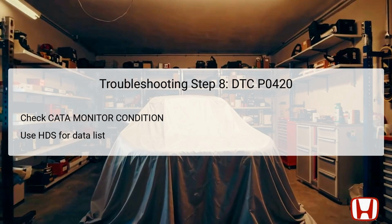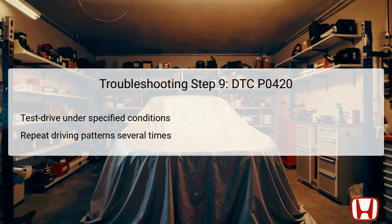However, if the condition is noted as no, it means further investigation is required, and you will need to revert back to the previous step to conduct additional checks to identify residual issues which may have been overlooked. For the 9th troubleshooting step, you will need to test drive the vehicle again under previously specified conditions. This includes ensuring that the engine coolant temperature, ECT, is above 158 degrees Fahrenheit, 70 degrees Celsius, and maintaining vehicle